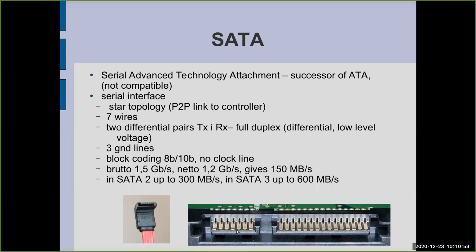The second issue is why the ground paths are longer. This is very typical for a technology which is called hot swap. So hot swap technology lets us connect a device when it is powered on. Otherwise, we would have to turn the power off the device and then connect it.